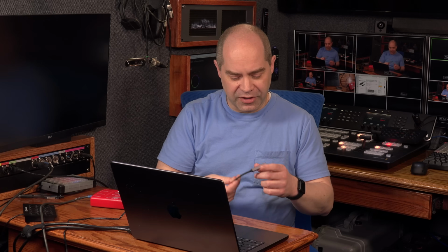Alright, the next thing that I wanted to mention is that we can use a different type of cable in order to connect our computers to our video production system and have better luck than some of the less expensive options that are out there. So most of the time, if we're dealing with a computer that only has USB-C, we can grab one of these little inexpensive adapters. It just goes USB-C to HDMI, and those will work. The way those work is they basically tell the computer, hey, use some of your extra USB pins to give me an HDMI signal, and then it's able to pass that through. These cables don't actually do any sort of conversion at all. They're just telling the computer what signal type you want, and that's reliant on the computer to generate that type of signal. Well, unfortunately with the Mac, sometimes it generates a signal that's just not readable by a connected device, and so you end up with nothing on your screen.